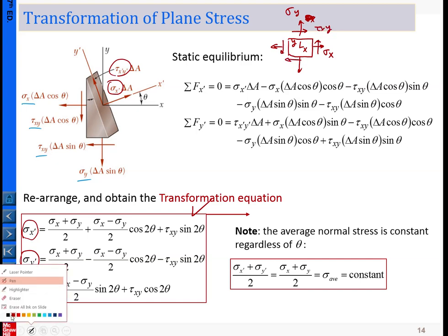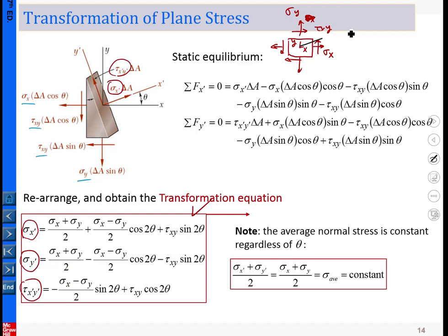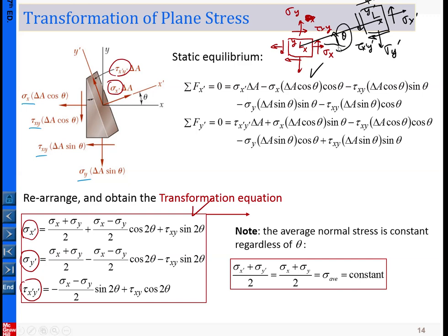And then we're going to determine, again, you see I'm going to use the symbols. Here, for example, this is theta. So in the new orientation, x prime and y prime, this is sigma x prime and sigma y prime, and tau x prime y prime, etc. I'm out of space here for drawing. So basically we are given this information, and we pick a theta value, then we calculate the three stress components, which are given in these equations.